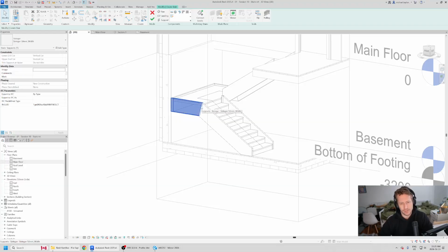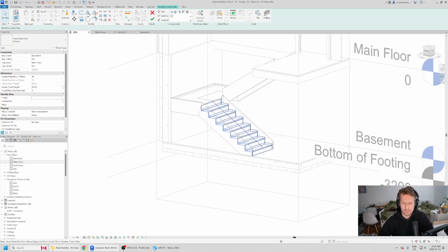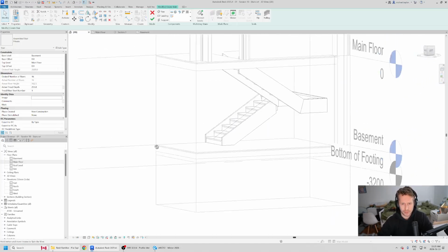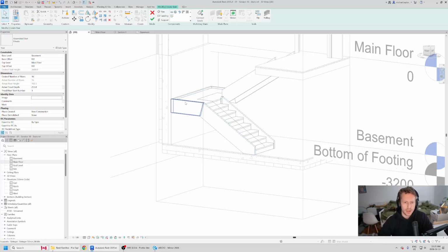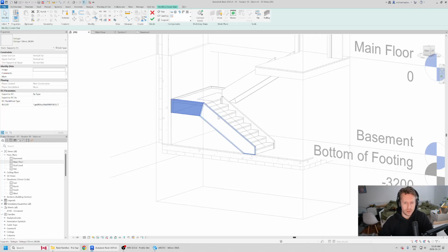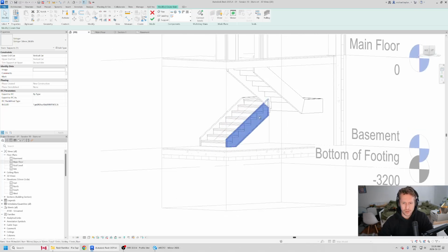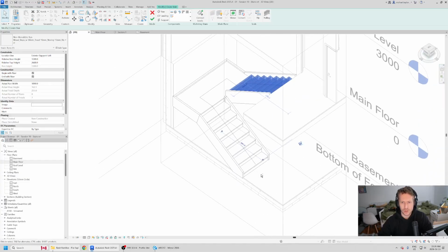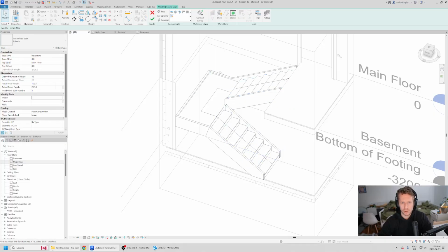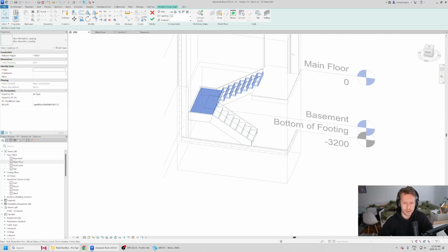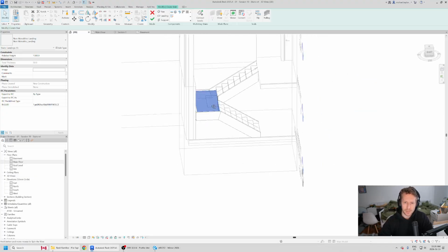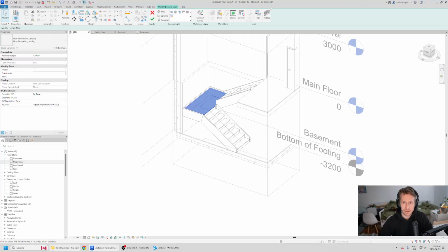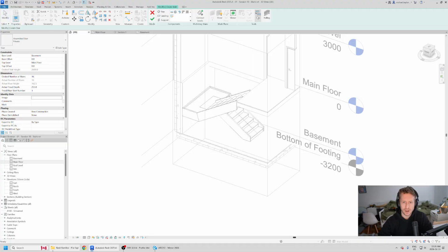It can get very complicated. So if you use it straight out of the box, no problem. But you'll see that there's lots of stuff that we can change, modify, hang out with. Here, this is the stringer. These are the edge supports. So these are the supports that I was talking about, the stringers. And in between them, we have our tread and our riser that are being supported by those stringers. Over here, we have our automatically created landing. And yeah, what we don't have yet is the railing itself. There is a nifty command here. If you've got it on the wrong side, you can flip it. I think that's pretty fun.